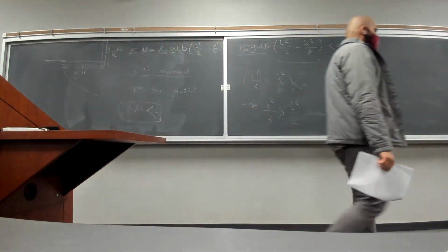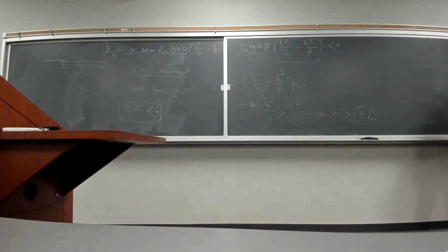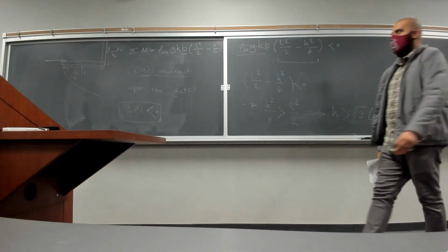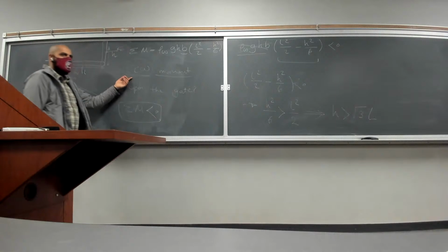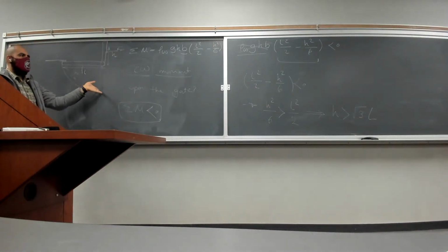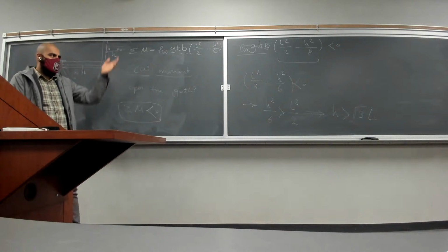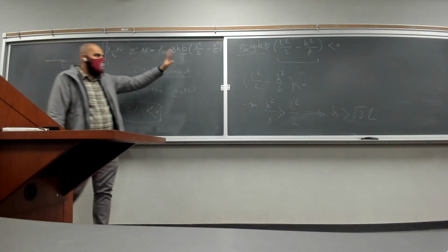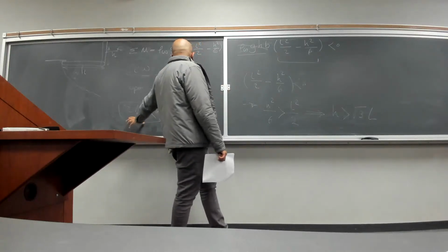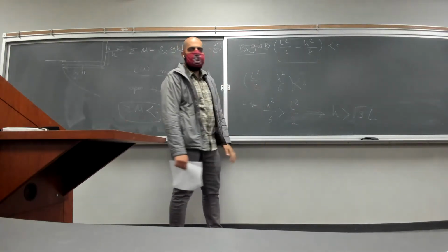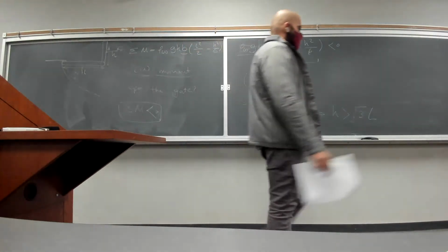So if we want to open the gate, the moment that the water is creating there has to be in the counterclockwise direction because it has to push the gate in this direction, which means that the total moments have to be negative. Plug all of those in. We have the equation, and we can plug the equation here for moment, and then we can calculate the condition. Are there any questions?